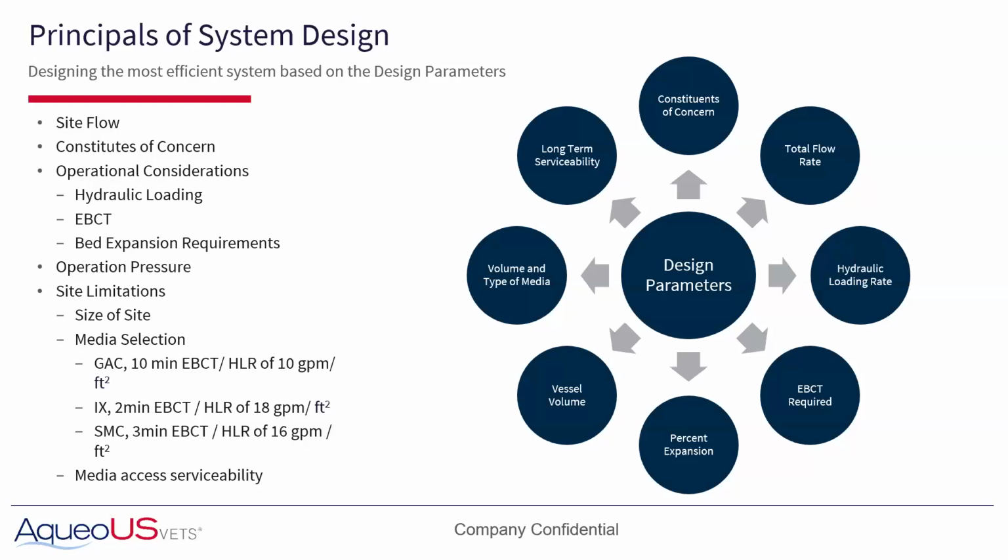The activated carbon, you're probably looking at 6 months to a year in some cases. The ion exchange resin is a little bit longer, a year to a year and a half, maybe even up to 2 years, depending on concentration. You have to be able to get that media out of the system, get the new media in, and obviously be able to service the vessels themselves.